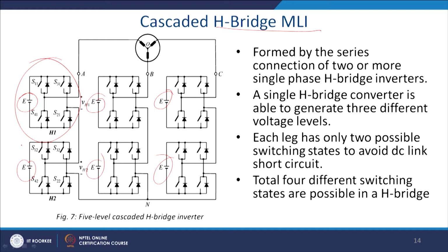Another problem is that we require to provide an isolated voltage source for each of these blocks or H bridges. So, we can say that it is formed by the series connection of 2 or more single phase H bridge inverters, a single H bridge or converter, whatever it may be.